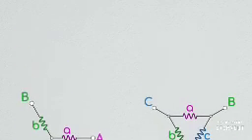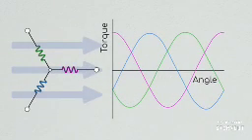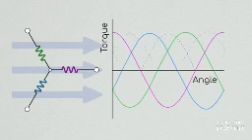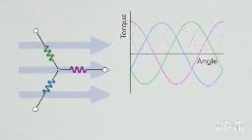If we were to look again at the torque curves for the 3 loops of wire revolving in a magnetic field and think about the case of the Y configuration, what exactly would we want? Well, at any time, we would want the loop which has the maximum positive torque connected to high voltage and the loop that has the largest torque in the negative direction connected to ground. In this way, the current will flow positively through the high positive torque loop and negatively through the negative torque loop, thus producing positive torque in each.